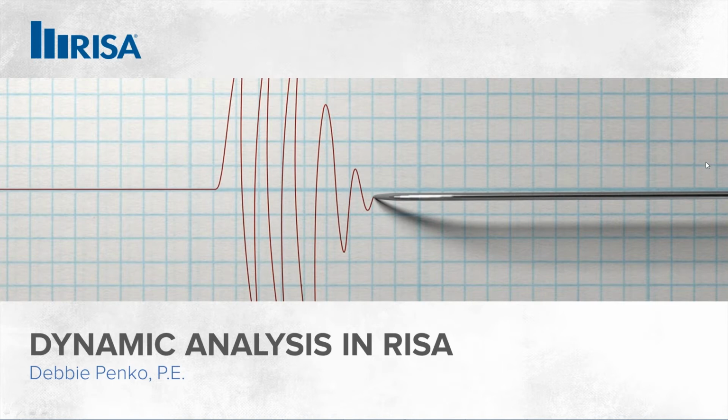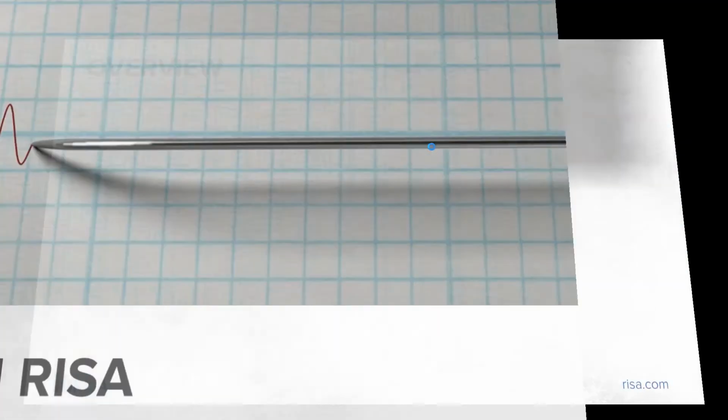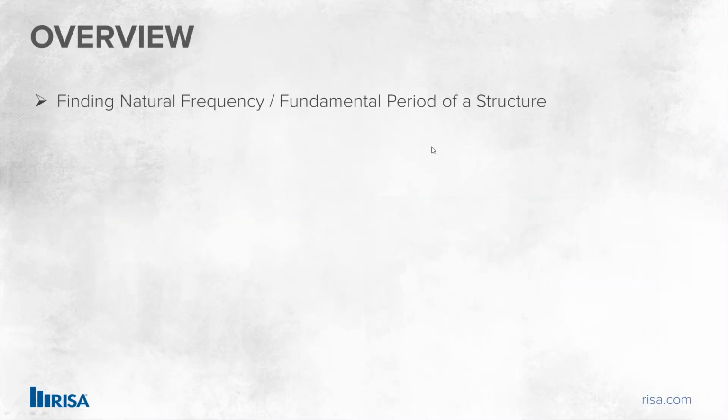The dynamic analysis will be referring to the calculation of the modes and frequencies of the vibration of the model, and the response spectra analysis will be using these modes to calculate the forces, stresses, and the deflection of the model. So as an overview of what we're going to work on today, we'll be talking about that natural frequency and finding that fundamental period of the structure, and that's going to be our really first stab at what we're doing here with the dynamic analysis.